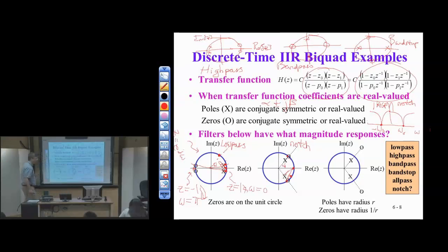So in homework 3.1, you're asked to filter a signal and noise, and you start with interference outside of the transmission band, and when you apply the filter, you'll get an increase in SNR because you'll attenuate the interference that's out of band. When you put the interference in the same band of frequencies as your signal, and you apply a bandpass filter, both noise and interference come through.